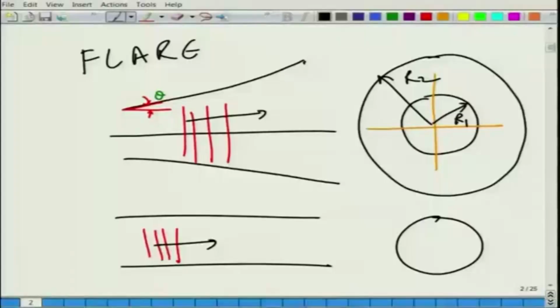reactive mufflers. What do reactive mufflers do? As I have probably noted in my third week's lecture, mufflers are categorized into two parts, primarily reactive mufflers and the dissipative mufflers. So, talking about reactive mufflers, they work on the principle of reflecting a significant portion of the acoustic power back upstream to the source, and allowing only a limited portion of the acoustic power to propagate downstream, at least for a particular given frequency range.